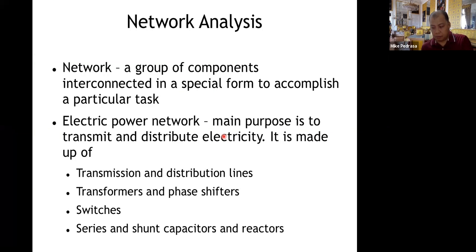For this class, our main topic is load flow. Essentially, it's just circuit analysis. We will look at the entire power system as if it's just a big circuit that we will analyze. The main problem with that is that the equations we will deal with are mostly nonlinear, or there are linear equations, but there are nonlinear equations as well. Take note that when we multiply voltage with current, the result is electric power. Because of that multiplication operation, the equations become nonlinear.